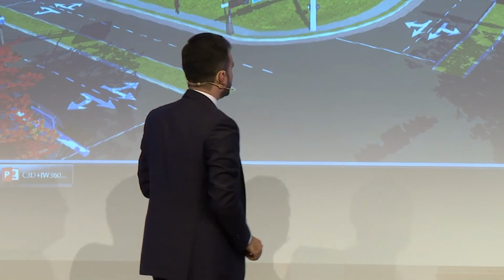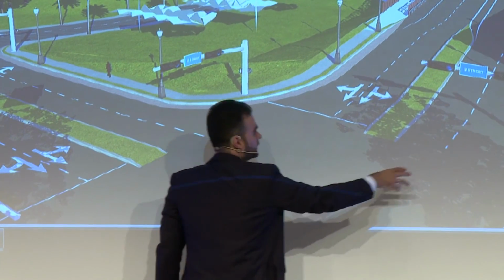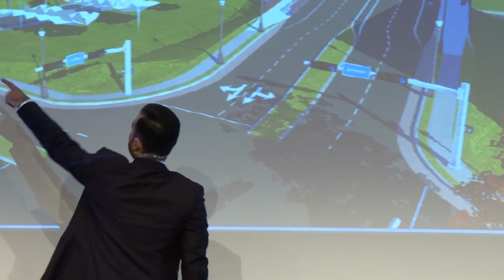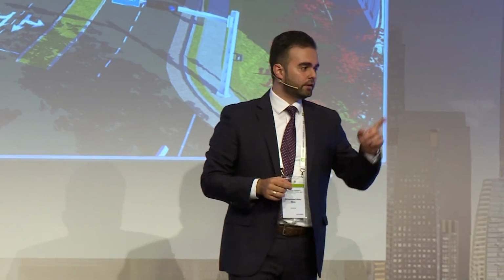And the other thing is the corridor optimization. Let's suppose I have a point here. We don't have those roads. And I tell the software, please connect this building here to that building over there. Show me the best road with the minimal cost, taking into account certain parameters. Think of it like generative design, the one that our vice president talked about today. You specify areas to avoid, things to create like a bridge if you go above 20 meters. It's actually very intelligent. And there are videos on it.